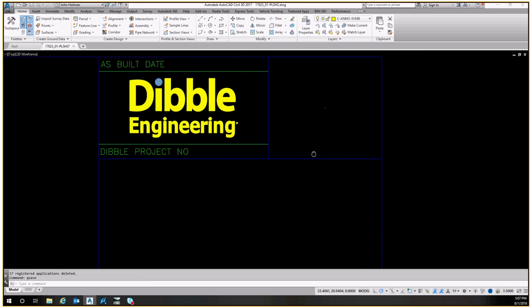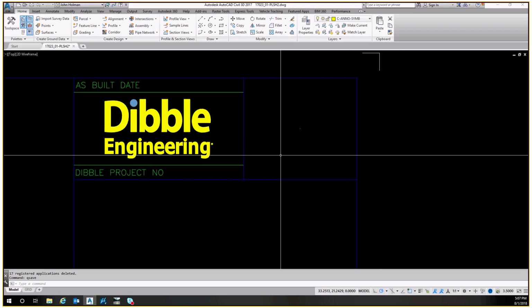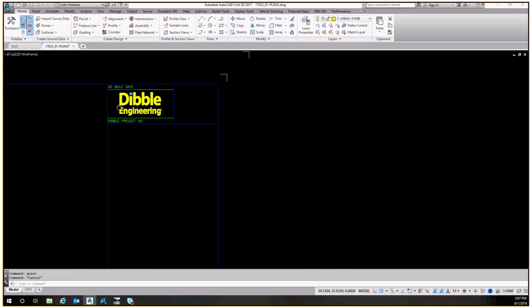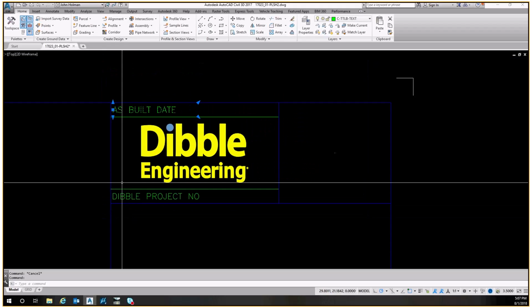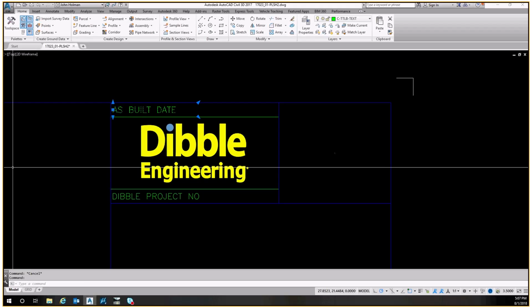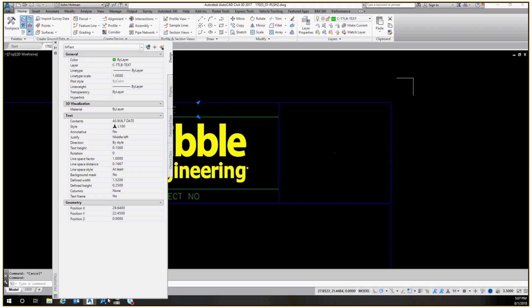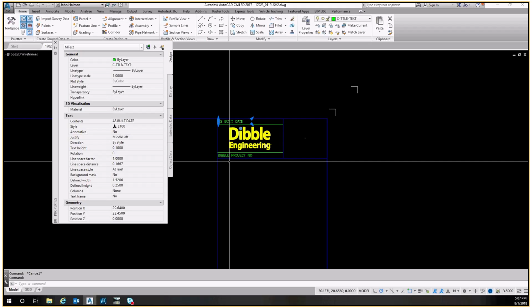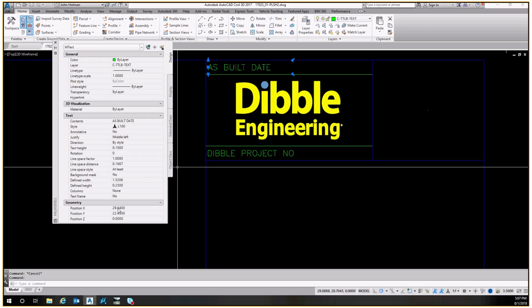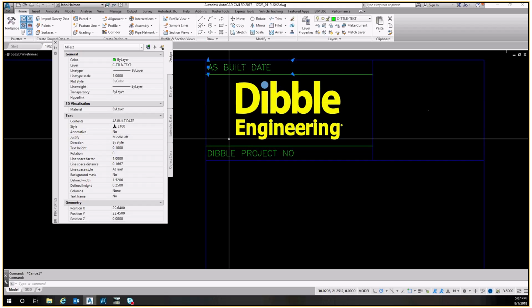And after that, let's just go ahead and start up here in this top right. A lot of these text elements, these green text elements here, are going to be placed at unrepeatable eyeball dimensions. So in order to combat that, this one actually in particular that I selected is good. 29.64 in the X direction and 22.45 in the Y. This one was placed